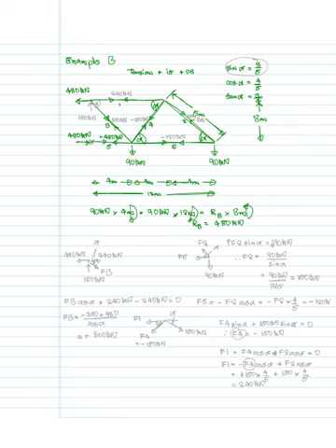So in terms of the vertical equilibrium now, we've got 180 kilonewtons acting downwards, and therefore since that member there can't take any vertical reaction, the vertical reaction goes up here. So we could say that value is going to be 180 kilonewtons.